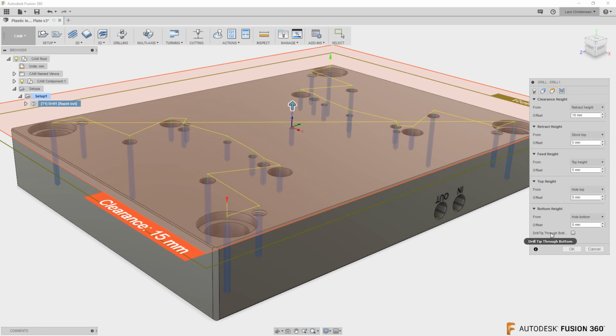You're always worried about how deep my tool is going to go, so start there. And you will see that in this case it goes to the hole bottom, and I'm just spotting right now for my drill. And by the way, most drills, standard high-speed drills, have a 118 degree cutting edge on them. If you can get tools that have a flatter angle, like 120 or 121, some of them you actually don't have to spot, but normally if you're using high-speed tools, you spot first.